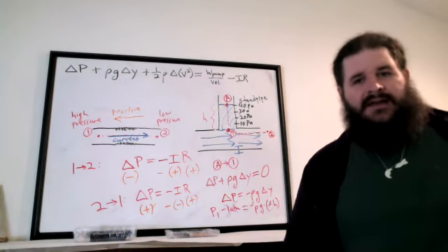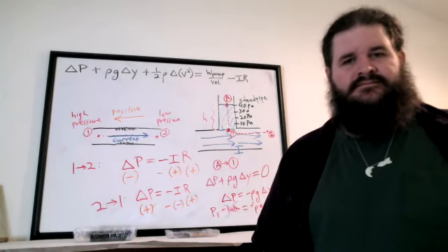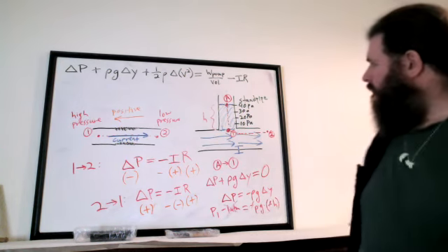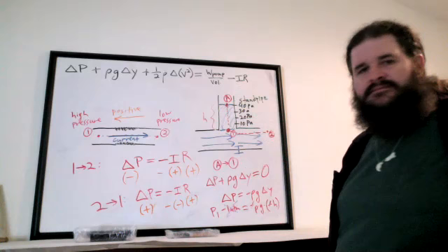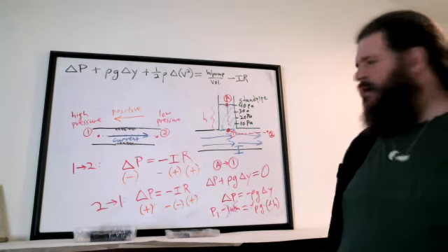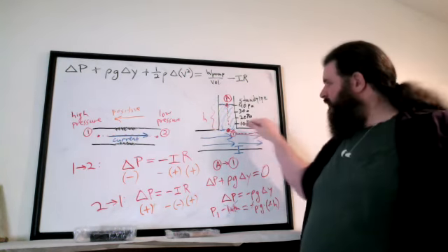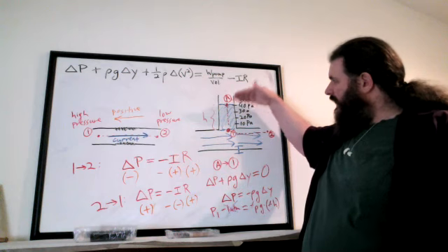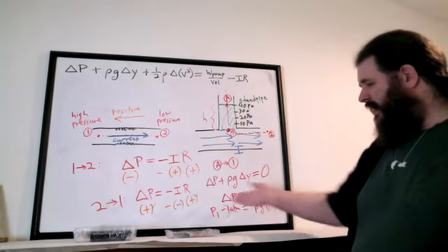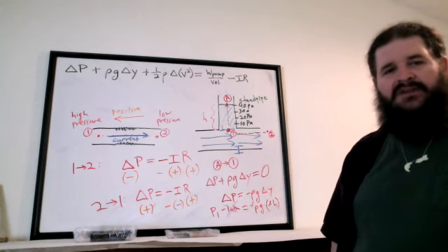All right. A quick question. Okay, go ahead. So when you're doing the gauge pressure, if we're trying to find the pressure for point 1, the height we would use is the height of A. Yeah, you'd use that height between A and 1. Basically, if you had a ruler taped to the side of the standpipe with 0 here, you could just measure how high in centimeters the water rises, convert that to meters, multiply by density and gravity, and you get the gauge pressure at point 1. If you want absolute pressure, you could just add 1 atmosphere to that.